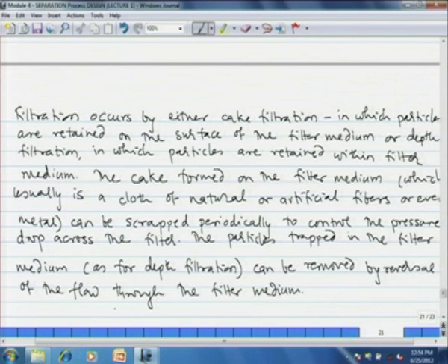the reaction mixture. However, the reactor effluent is at high temperature, 1300 degrees Fahrenheit, and at high pressure also, about 500 psi. We first try to recover the heat of that particular stream through different exchangers. That whole topic will be covered in the module on heat integration of the process, and then we go for phase splitting.